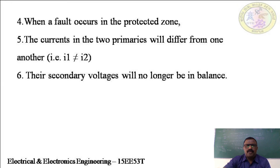Let us assume a fault occurs in the protected zone. Whenever a fault occurs in the protected zone, the currents in the two primaries will differ. In healthy condition, when you don't have any faults, I1 is equal to I2. When you have a fault in the protected zone, I1 is not equal to I2. Their secondary voltages will no longer be in balance. In previous cases, whenever I1 is equal to I2, the voltages are in balance.